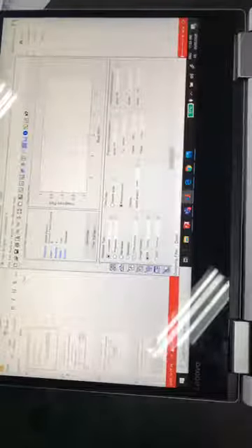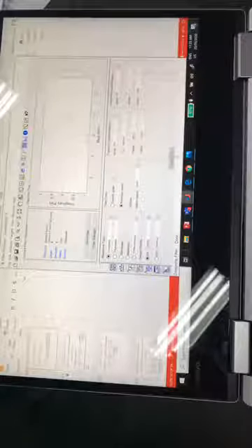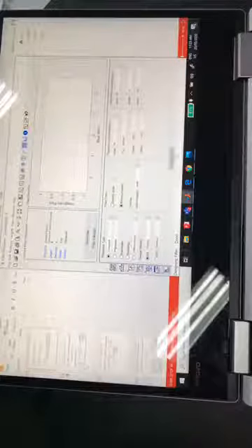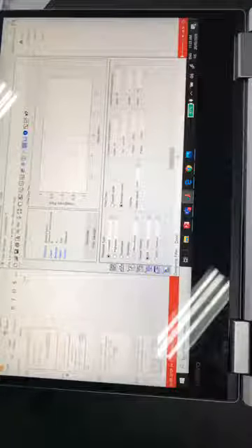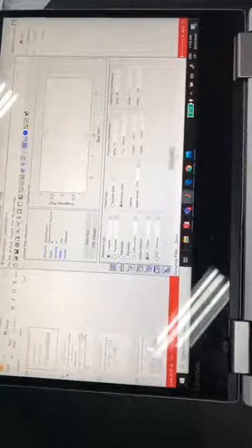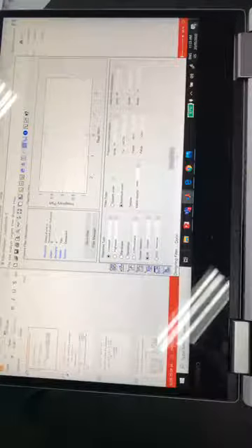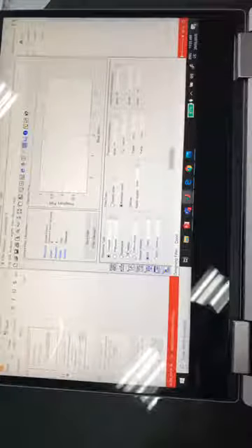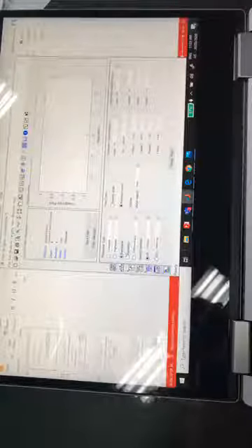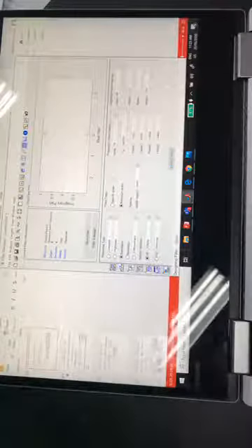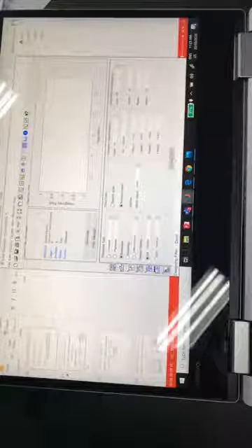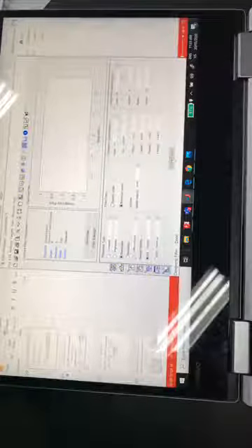So this is important, that just by looking at the pole zeros, we can guess whether the filter is a low pass or a high pass or a band pass. For example, if I do a band pass, what do you expect to have? Where should you see the poles? So okay, let's look at the band pass. Band pass filter design, and precisely this is what I was expecting. The frequency which I want to let pass, there are poles, and frequency which I want to stop, there are zeros on the unit circle.